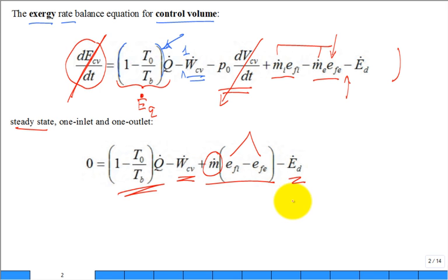And then the simple equation: if you already know the rate of entropy production in the control volume, you multiply that by, hey, I forgot, what is T naught? The dead state temperature. It's a very simple relationship, a 1-to-1 correspondence. If I have irreversibilities, I'm going to have some entropy production, and I'm going to have some destruction of Exergy.